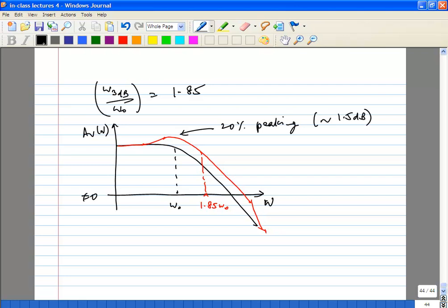So what you may want is a maximally flat response for magnitude. Let's see. Again, you can go back and try to find out the value of m that you would need for a maximally flat response. How do you do that? One easy way is to give a constraint that at omega naught, the value of the transfer function should be the same as the DC transfer function. That is one way to do it. To say no peaking. Actually, I won't even say maximally flat, I'll say no peaking. That's not necessarily the same as maximally flat. So let us start off with no peaking first.